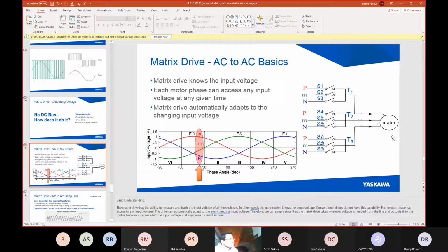But because we're not hitting the motor with full voltage pulses, we have a bit better ability to shape that current waveform. In addition to pulse width modulation, we have a rudimentary pulse amplitude modulation, and as you'll see later, it's a 3-level pulse amplitude modulation.